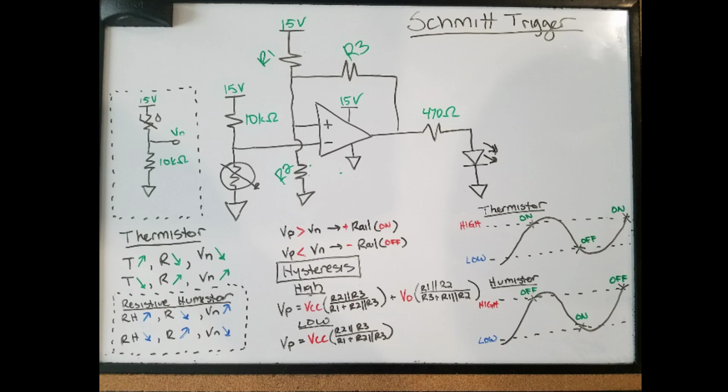So for my variable resistors, I essentially looked up the part, searched out the data sheet, and found the resistance values at my specific ranges. And I used those values to determine the subsequent values of R1, R2, and R3 for the positive feedback.